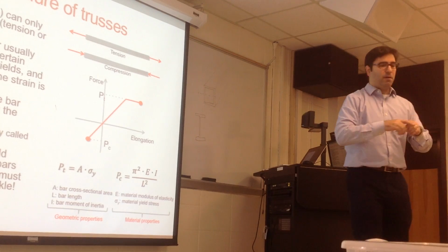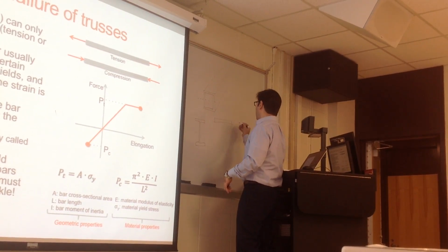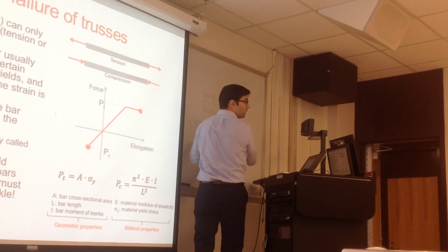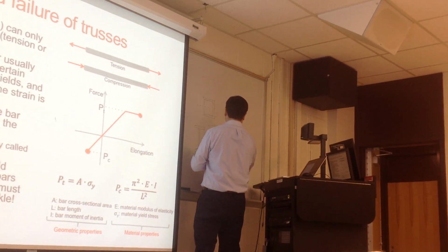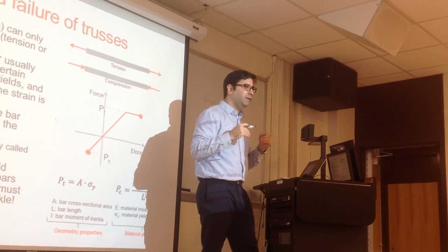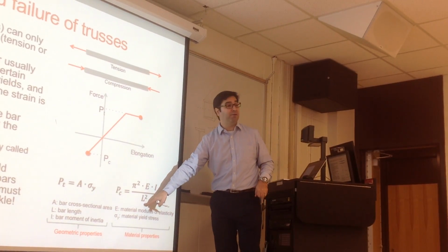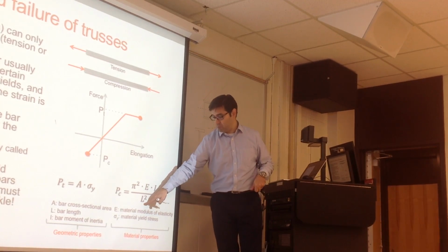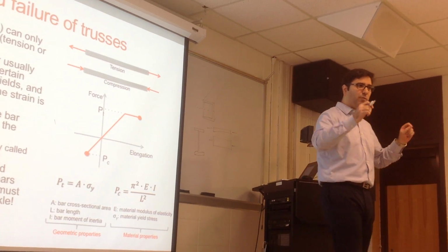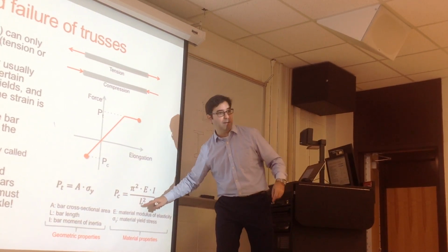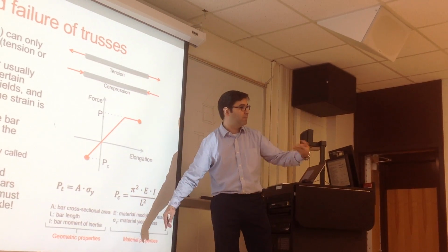So if you have this bar, it buckles, let's say, under this load, and now we make the bar higher like this, you will probably not buckle. You can see intuitively how that works. The other thing, and it's very important, with a major impact because it's squared, is the length of the bar. If you make your bar long enough, you are increasing L, and in a quadratic fashion, so you are decreasing the load by a large amount.